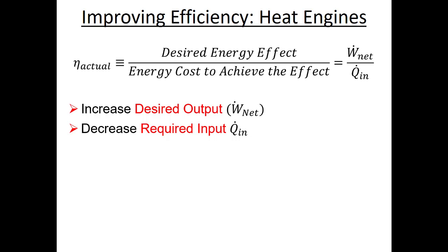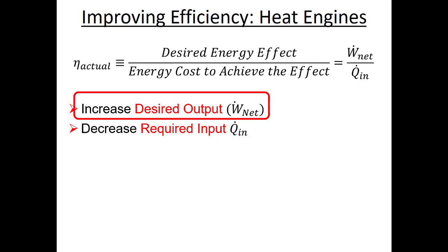So we're going to talk about reheat cycles today. Even though reheat cycles increase both of these two things, they increase the net power faster than they increase the heat in. So I think of the modification to do reheat as increasing net power in these cycles, even though, as we see, they'll increase both net power and heat in. Sometimes if you're looking at a cycle with one turbine, and one turbine is good, maybe two turbines would be better.